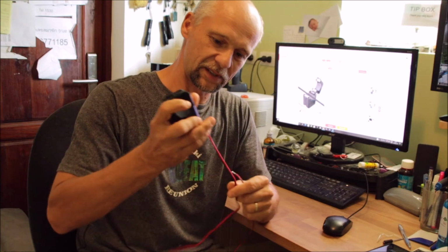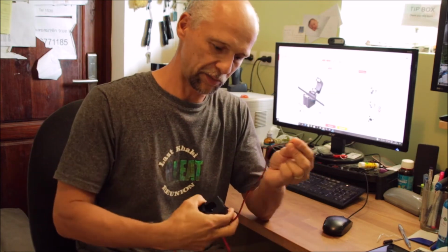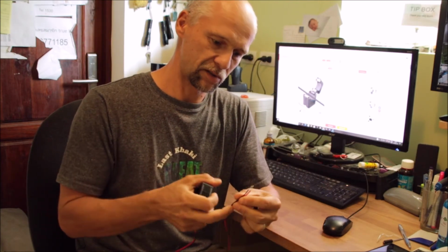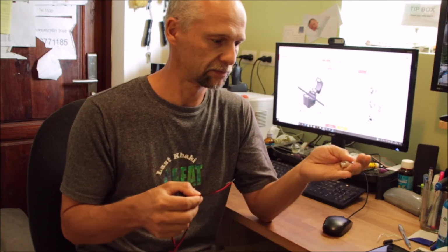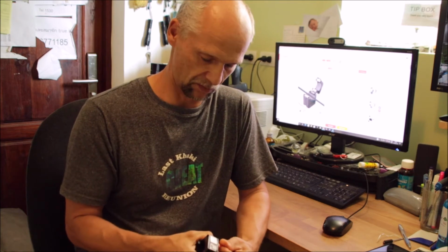Okay, so unfortunately this CT only comes with a 1 meter cable, so this is not enough for my distance between the main distribution board and the battery cabinet. So we will add an additional meter of wire, and then it should be enough. So 2 meters from point of measurement to our inverter. That should be fine. Okay, so let's go and get a soldering iron and some heat shrink, and we build this.